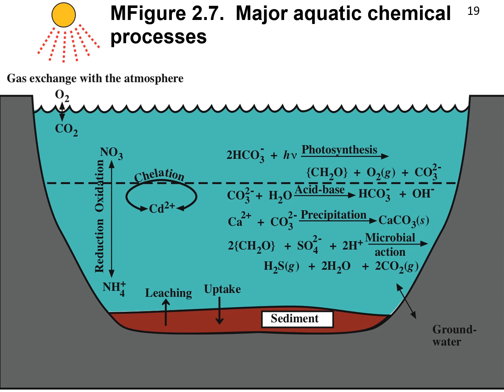For now, it's worth pointing out that in most cases within water, the things that we might want to measure are parts of dynamic processes that will make molar units the most convenient to work with. However, engineers hate molar units, and most contaminant limits or design specifications will be given in mass percent units, or the very closely related parts per million or parts per billion. This figure shows a number of significant types of reactions that occur in water. And for each of these, if we're truly going to understand how an element, ion, or a molecule exists in solution, we're going to need to use molar units.